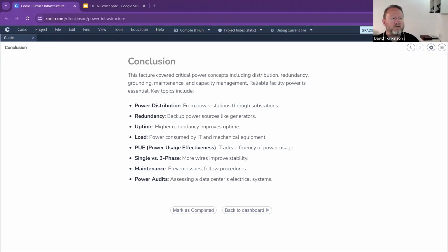Oh, there's a good question. How many types of RCDs are there? There's loads of different types of RCDs, and the RCDs all have different ratings, which are based around the amount of milliamps, that is milliamp change detected, and the speed at which it cuts off. So there's two ratings for RCD circuits, the milliamp detection of change and the speed it is designed to cut off.